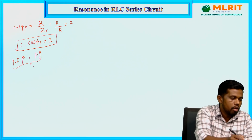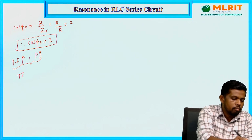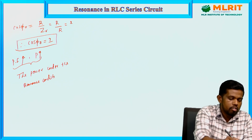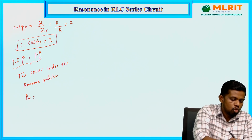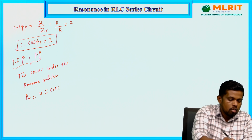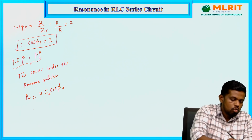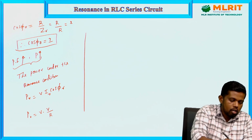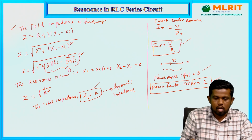So based on that, we need to find the power under the resonance condition. The power under the resonance condition is equal to V into I cos phi. This is the active or useful power taken by the circuit. Under resonance condition, this means I r and this means phi r. So we substitute all these values. Then P r equals V as it is, and I r equals V by R according to Ohm's law, because we have derived the current value under resonance condition.